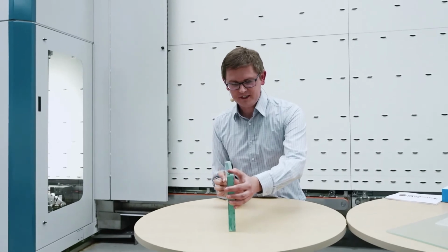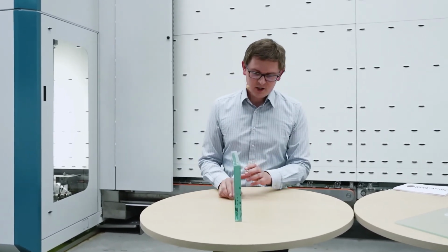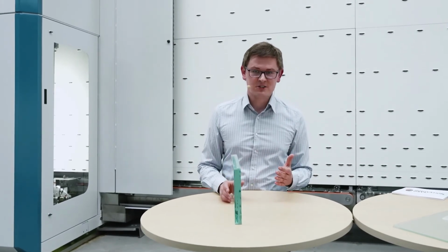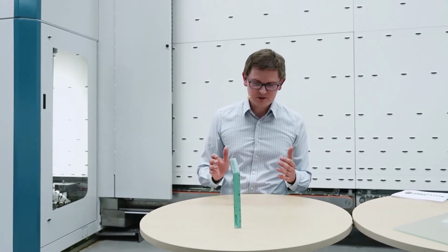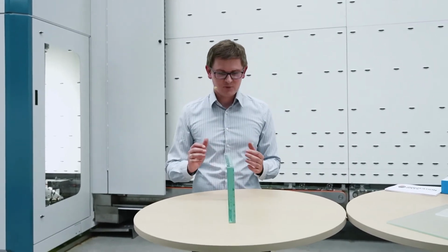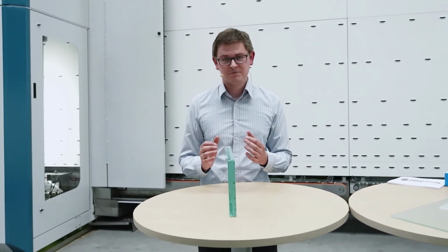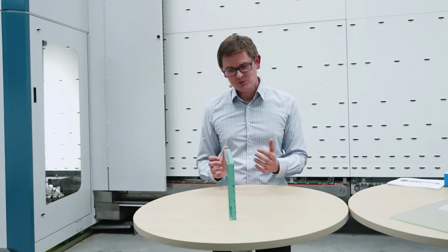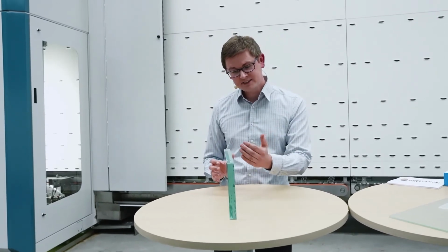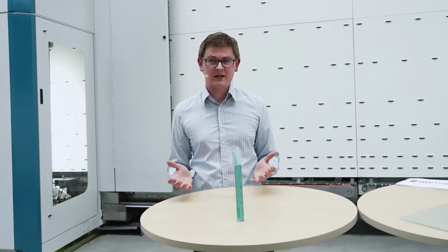And usually thicker glass panels are very uneven. Here we have a big advantage with our technology. Because we use two separate tools, one for the front and a second one for the back, we have the opportunity to follow every glass edge individually. That means at the end you will have a very even aris glass as well as an equal wear on your cup wheel. And that's really great.